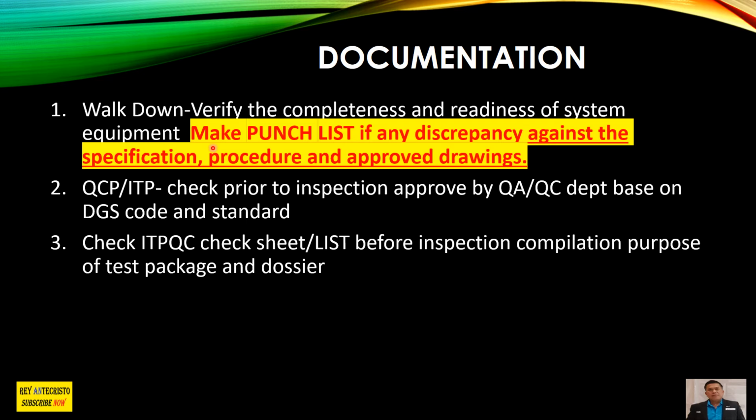As for me, I'm a client right now, so I'm working as a client. The contractor brings the MC dossiers to me, and they also bring the RFC documents. That is the commissioning dossiers. Remember, there are two separate ones: the mechanical completion dossiers and the commissioning dossiers. Okay.